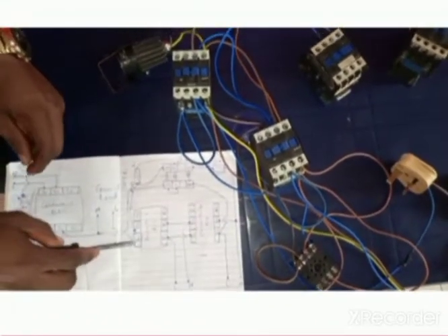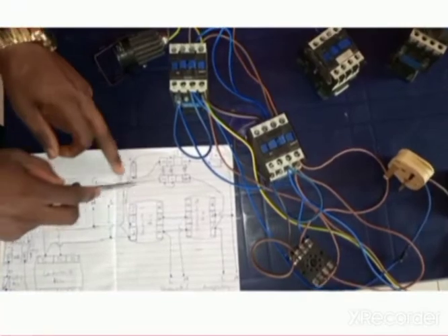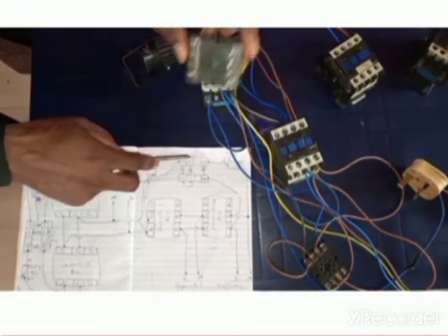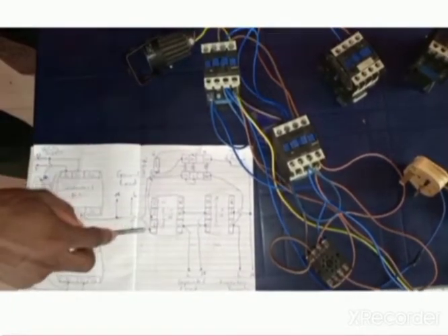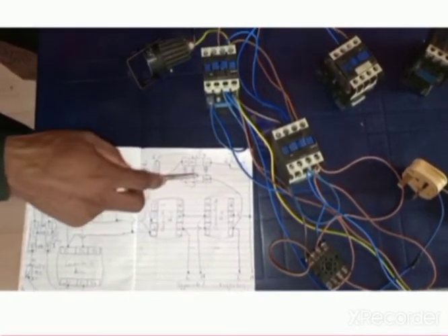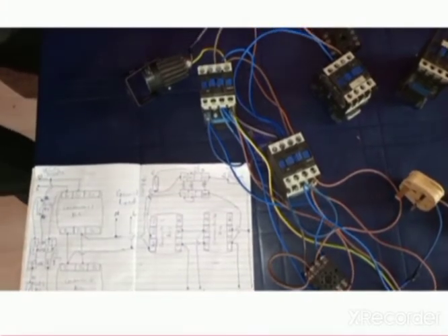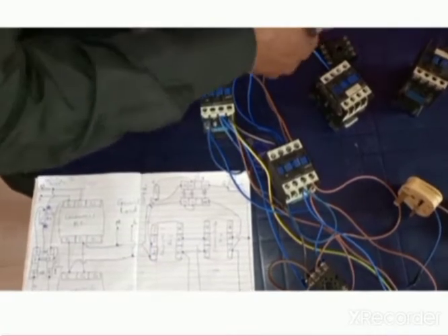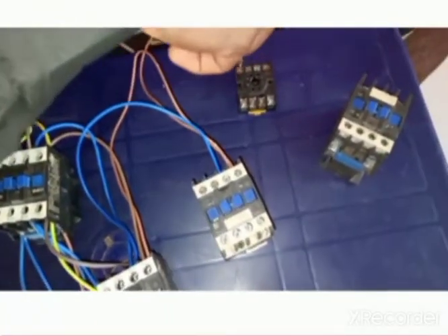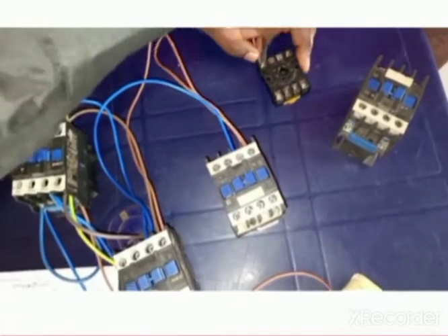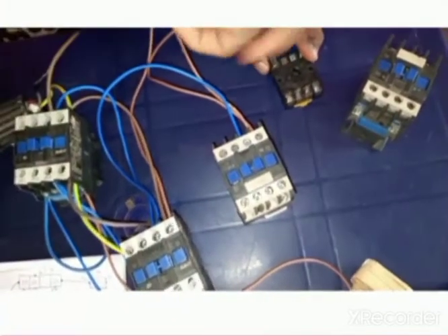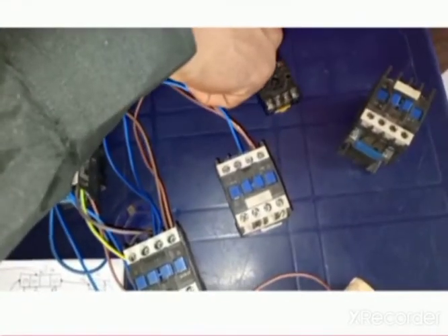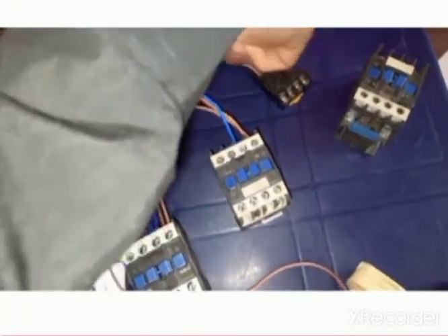So looking at it, you see that L1 of this contactor 3 connects to where? 2 of the second pin relay. This is the pin relay 2, the 8-pin relay. So we see that L1 connects to 2, from 2 to 1. So let's connect L1 to this. So we have to connect this L1 now to terminal number 2 of the 8-pin relay. So from the L1 of the third contactor to number 2 of the second pin relay, that's pin relay 2. Then from number 2 of the pin relay 2 connect to terminal number 1 of the same pin relay 2. So we are connecting to terminal number 1.